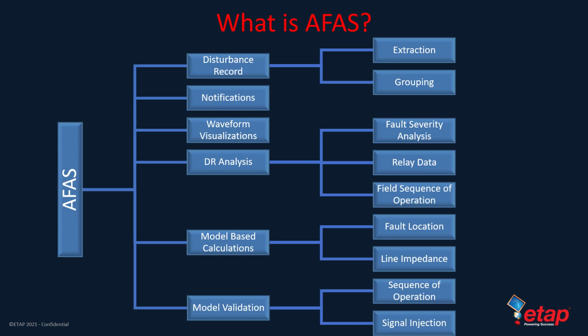Then these are grouped together using time and the electrical model. So if you have two incidents that are separated from one another in time, we know that those are two separate incidents. However, if you have two ComTrade files that are received at around the same time in the same area of the network, we know to group those automatically because we have a model-based solution. Notifications are built in, so emails and SMS are sent out to indicate what has happened, that we've generated an incident.